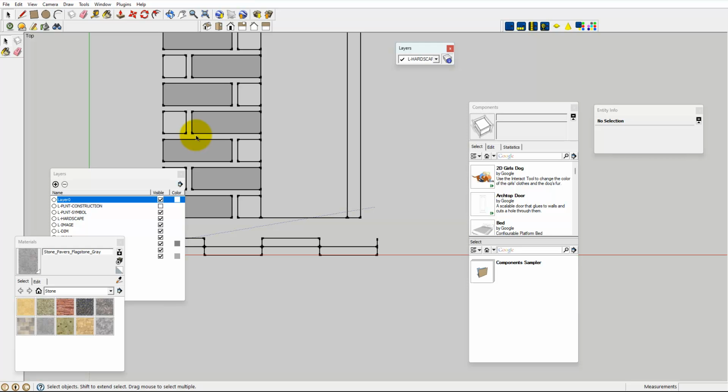So that's the second way of creating SketchUp models quickly and easily, exporting a drawing exchange file from gCADPlus and bringing it into the SketchUp environment. And it's very easy for us to edit within this quickly established model.